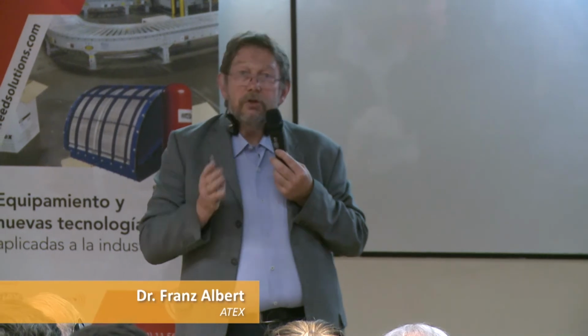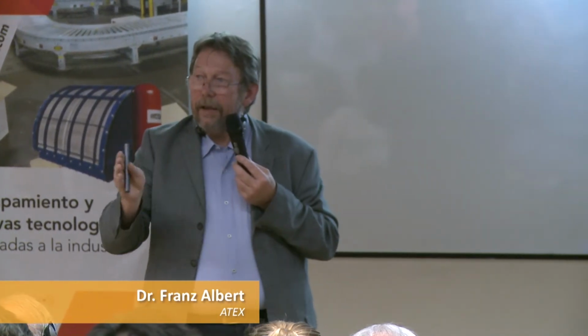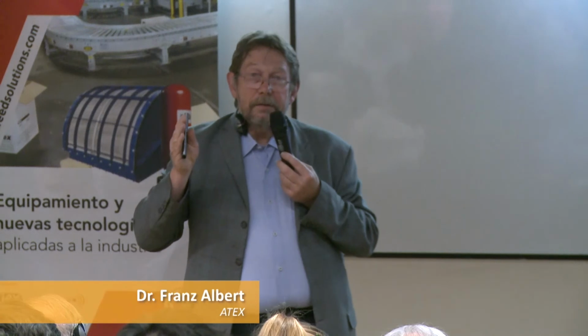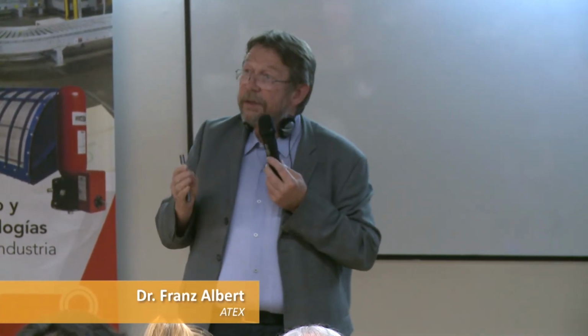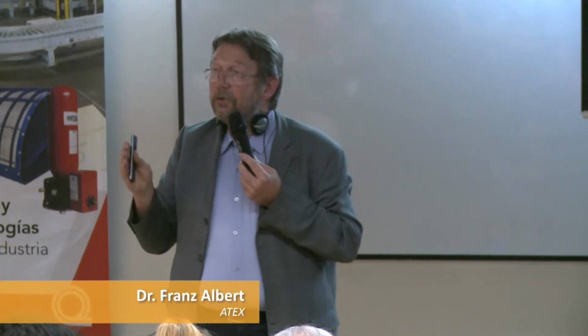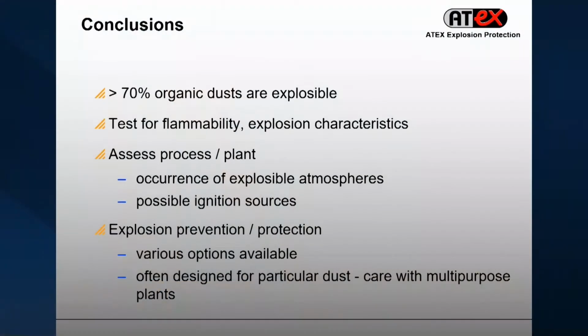So one really should go into detail and ask, what do I have here? Do I have an explosive atmosphere that is continuously there, or is it only there for a very short time? That will influence what kind of protection methods you can use.